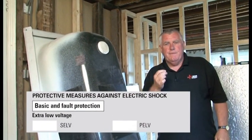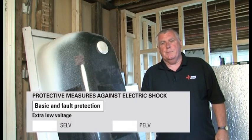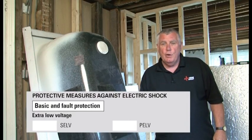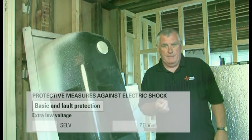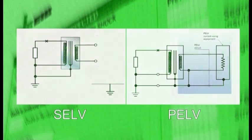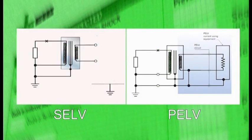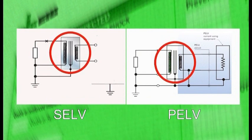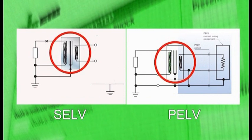Under basic and fault protection, we first have the protective measure extra low voltage provided by SELV and PELV. These two protective measures are very similar. In this diagram we can compare SELV and PELV. In this case, the extra low voltage source is a safety isolating transformer.